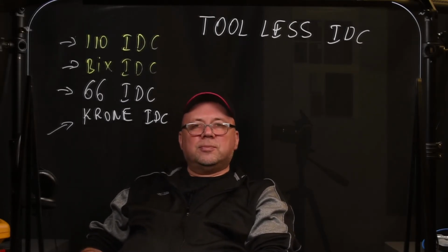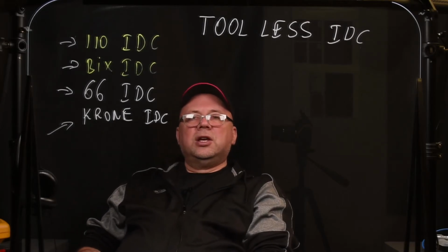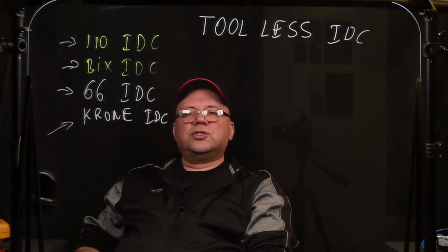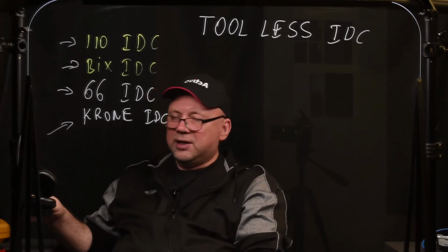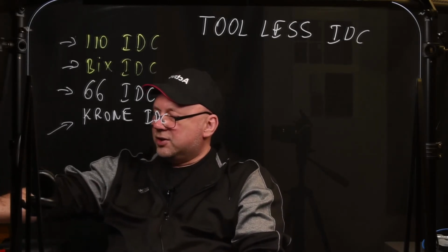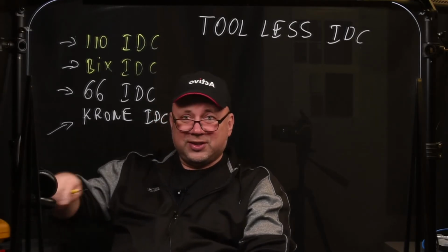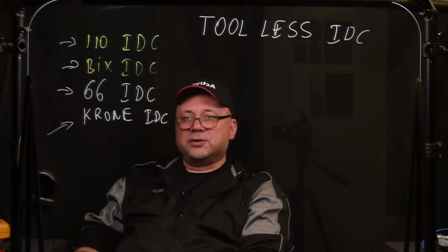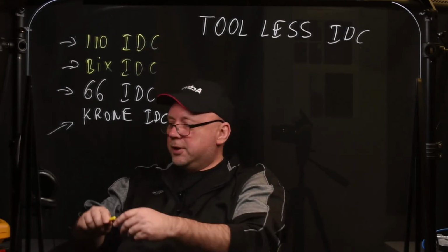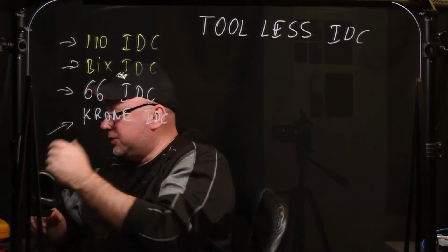In some cases, mostly when you start Cat6 and up, you're going to be asked to certify those cables, and certification is basically you're going to get some more expensive equipment to actually certify it, because the tests that the equipment is going to perform are going to be more precise and more rigorous. Okay, so that's basically the link.